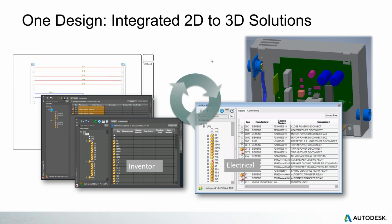And one of the key things I want to mention as well is Autodesk and Inventor have one design. They are 2D to 3D solutions. We have a live syncing tool between the two of them. So as I'm creating the schematic in AutoCAD Electrical and working on the information there, that wire connectivity information is then transferred into Inventor to help create a 3D model and path the wiring through the 3D model spots.